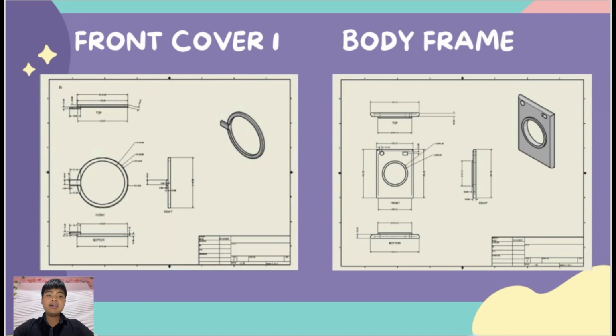And also the length of this machine for the left and right sides is the same, which is 850 millimeters, with the base at the top being 630 millimeters and the downside 570 millimeters. For the bottom side, the value of the chamfer is equal to 50 millimeters with the base of 630 millimeters, with the diameter of the circle equal to 440 millimeters.